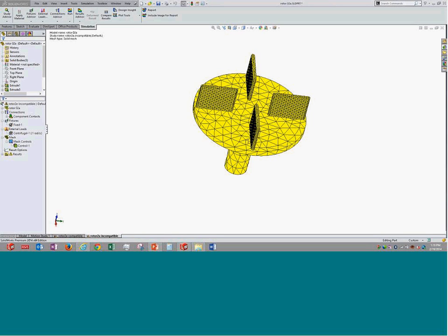The question says, if we experience a problem of solid mesh in a normal case, can incompatible mesh make it work? And in what way does it affect the analysis? Typically, compatible mesh is far more continuous and accurate. In incompatible, when we are writing equations, you have to change the stiffness of the body, so there is a small change in stiffness.